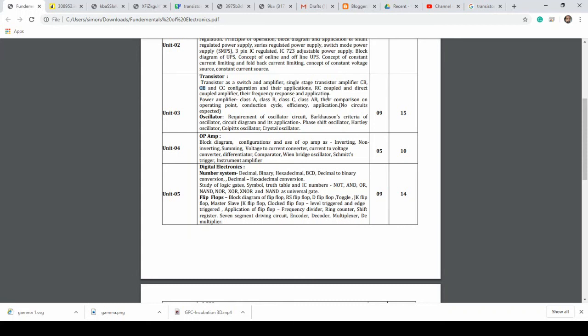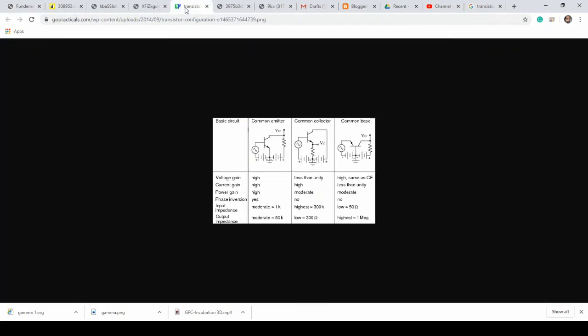We talked about RC coupled, where you have a resistor and capacitor circuit, with a capacitor in series and a resistor in parallel with your input. This would be an application when you're talking about AC filtering. AC passes through and DC is being filtered out. You're talking about AC, mostly amplifiers. We're not talking about DC. It's mostly AC. So those are the ones that we talk about, RC coupled amplifiers. We also saw an application where we talk about direct coupled, when you saw 3 transistors connected in cascade, and the gain was direct coupled. There were no capacitors in series.